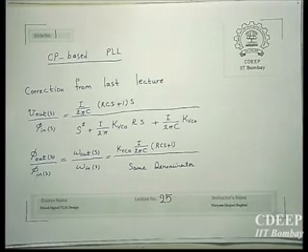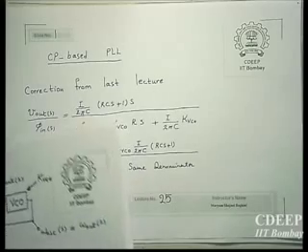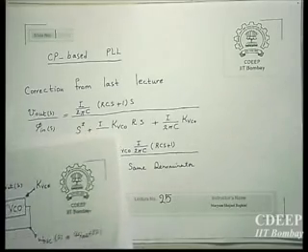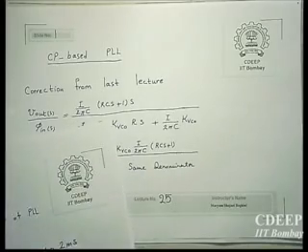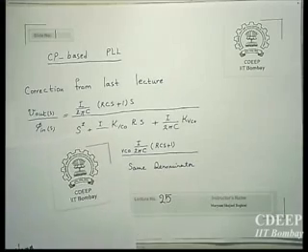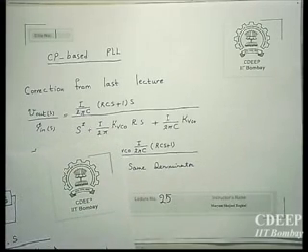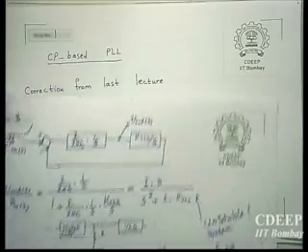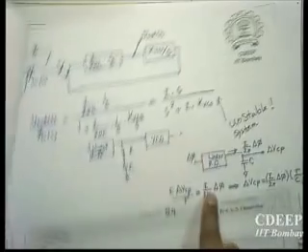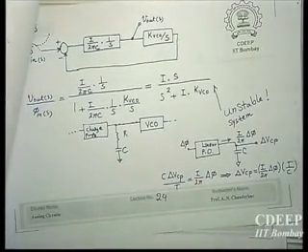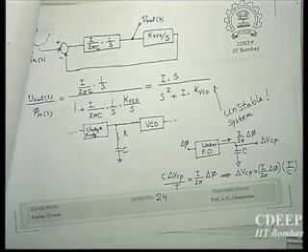But if you look at very low frequencies, if you look at this main transfer function, so it is like this when there is no R. And because of this, system was not stable because we had pole on the j omega axis.